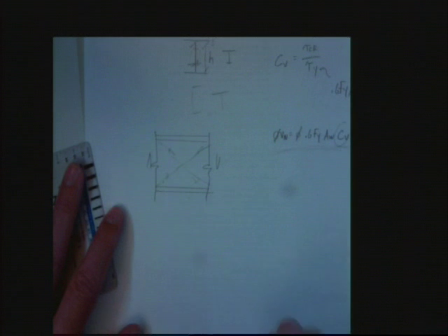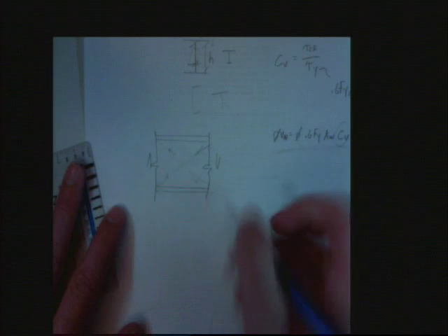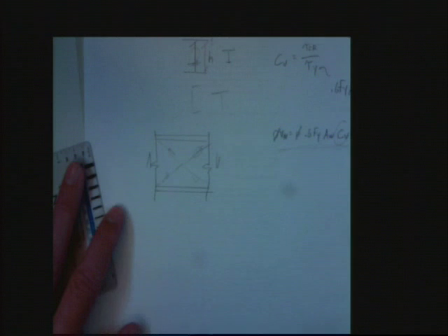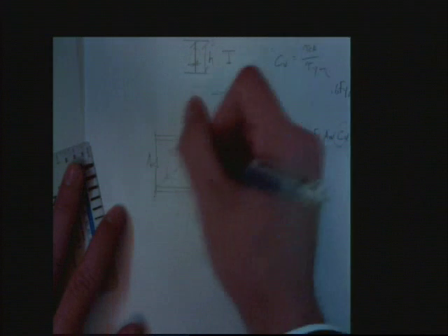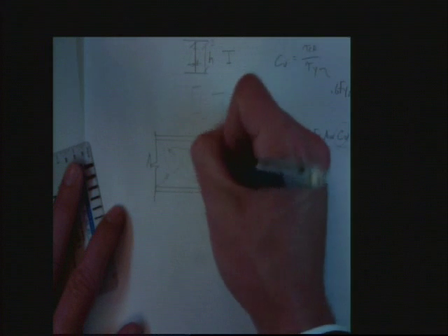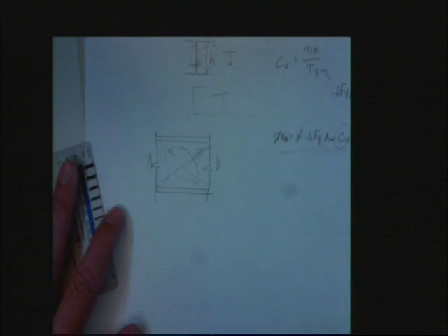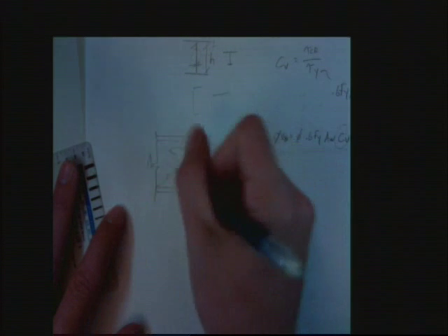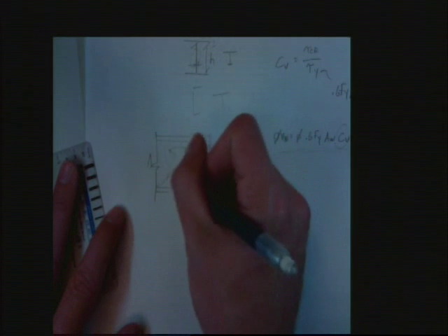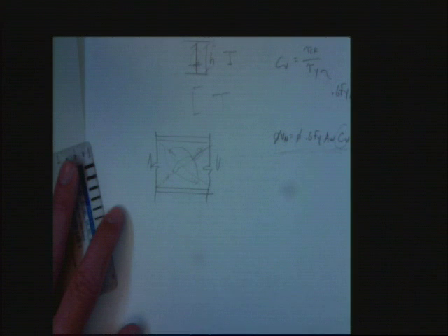We would say the first event, because it really truly is an event-to-event analysis. I mean, it really is. I know we talked about it with beams, but you had a homework on event-to-event analysis. Truly, the first event is the buckling of this member right here, right? And it looks something like this. We showed the sandwich bag, right, where we racked it. It looks something like that. It's where there's a bend or a buckle in the plate, right? But it's not over, right?